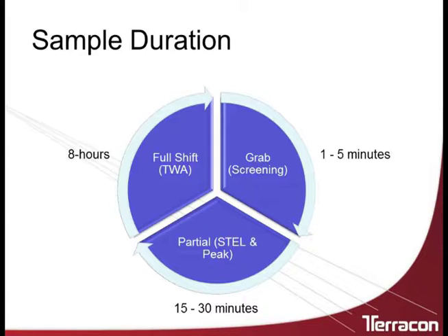You also have partial, which now we're getting to some of the OSHA requirements with respect to exposure limits. And the partial usually is to determine either a short-term exposure limit, or a STEL, or a ceiling concentration. Usually these are short-term samples, so you're collecting the sample over a 15 to 30-minute time frame.